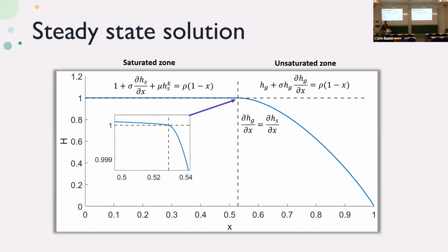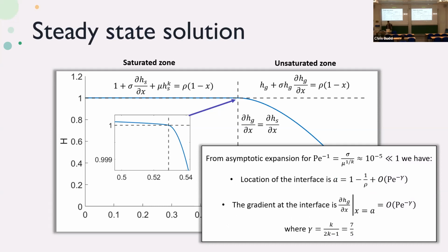The one thing that we analyze is the steady state, because we wanted to take a steady state as our initial state in the simulation, steady state of the groundwater for some mean rainfall, and then see what happens if we turn on a more intensive rainfall. Can we see how a more intensive rainfall turned on at some point would affect the flow that we observe in the river? So in other words, what will be the hydrograph of the river flow when we turn on an intensive rainfall starting from steady state conditions?